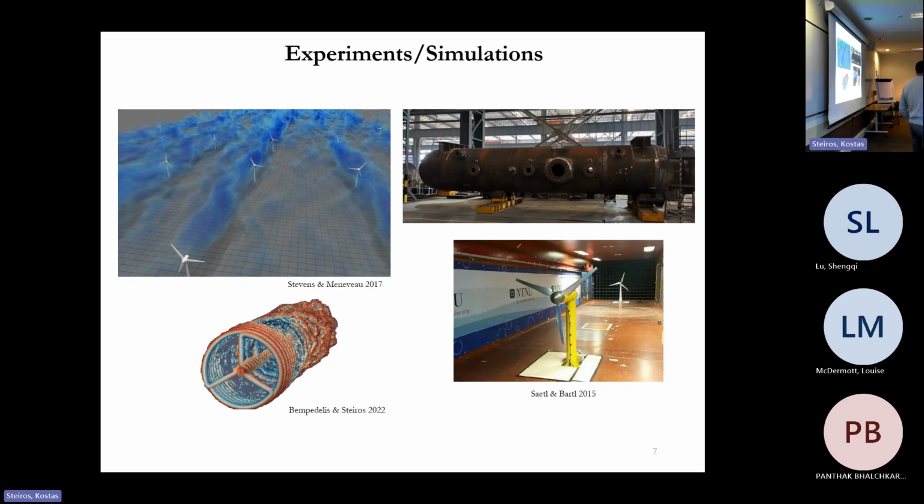Well, for that, we can construct specialized wind tunnels. So this is the wind tunnel that I designed in Princeton as part of this winter explosion that I was in. The idea of this wind tunnel here is that it has pressurized air inside at 100 bar. And by doing that, you can increase the Reynolds number 100-fold, so you can start matching the Reynolds number of the wind turbine. Even if you have a miniature wind turbine, the Reynolds number that it experiences, the physics that it experiences, are those of 100 times larger, right? So this partially resolves that. Of course, this facility is extremely expensive and extremely time-consuming to operate.